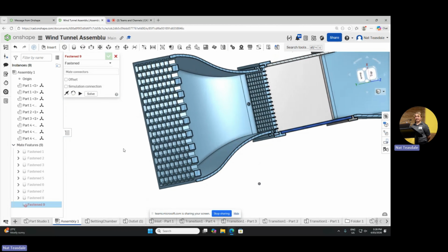When we look at things like our honeycomb design, or we look at things like the squares, you may be asking, why do we put the honeycomb in a certain area? Why do we put the squares in a certain area? There are a couple reasons behind that. So the honeycomb is specifically placed before we accelerate any airflow. You can kind of see that airflow will be accelerated as we go into the inlet, which allows us to generate a greater velocity.